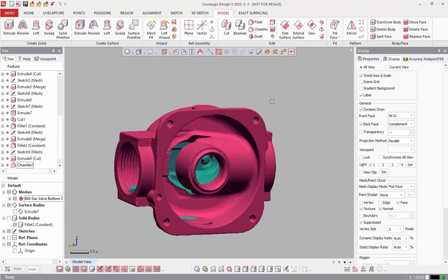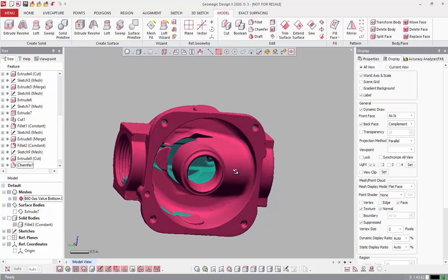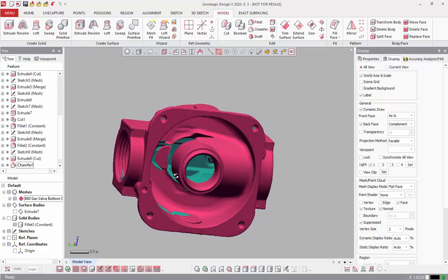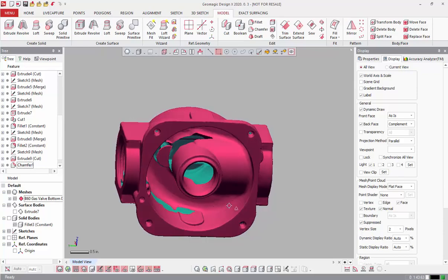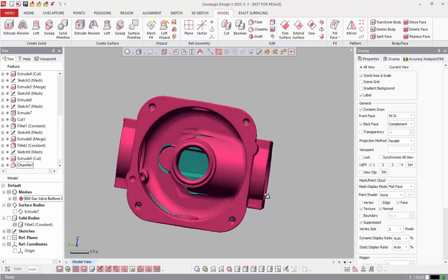And in a lot of 3D scanning software, especially reverse engineering software, that's not an easy thing to deal with. Trying to figure out how to fill holes and work with other areas is generally going to be fairly difficult. And a lot of those software packages do require something near a watertight mesh in order to generate a solid body model from it.